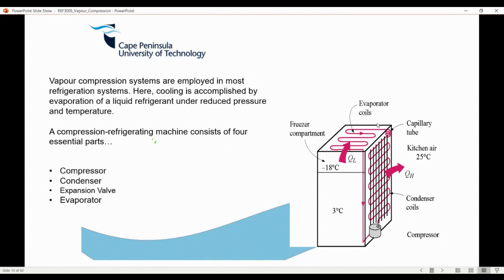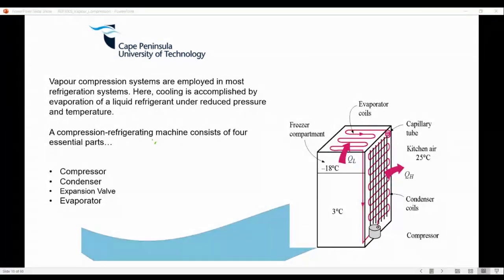Furthermore, you might ask where your evaporator is. Your evaporators are hidden within the actual fridge, where your food is sitting. The evaporator coils are there, responsible for extracting heat from the food. Then it rejects the heat at the back. So the heat you feel behind the fridge is the heat from the food you've put in, or the environment itself. Is it all clear to everyone? Was it explained well, as a layman, for everyone to understand? Can you give a few thumbs up? Are there any questions on how a fridge works or the refrigeration cycle?